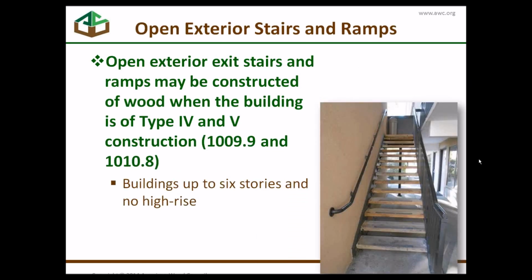Can you have a wood open stair on the exterior of a building? Yes, you can. When the building is type 4 or 5, there's a height limit, but the height limit is basically high rise. But if you have a type 4 or 5 building, you can have an exit stair with wood open risers on the exterior of your building. Here's the code sections to go to check all the restrictions. There's not many in this case.